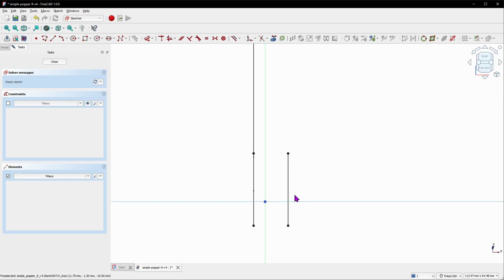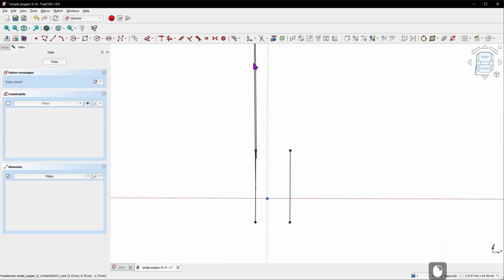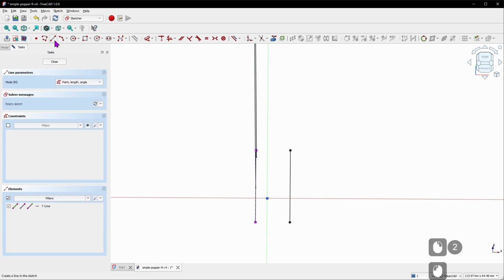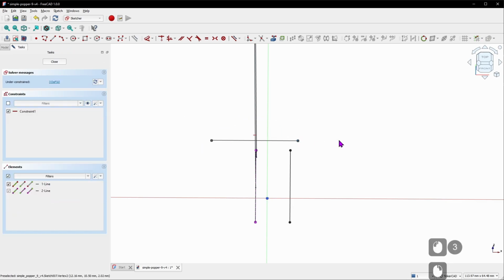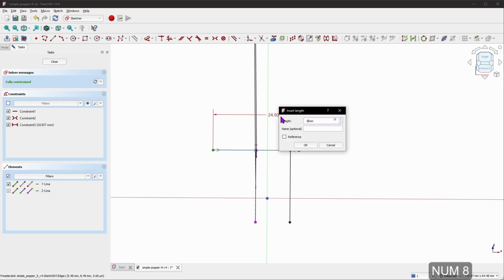Okay, our sketch is in the right plane, and if we rotate it a little bit, you can see that this line over here is the line that we would like to build our sketch against. So let's bring in the external geometry of that placement line, and we'll start to build that diving lip. Let's do a horizontal line here and select both of those points and that point and make it symmetric. And let's give that a dimension. Let's go 8 millimeters, and let's give this a name of back width. We will use that later.